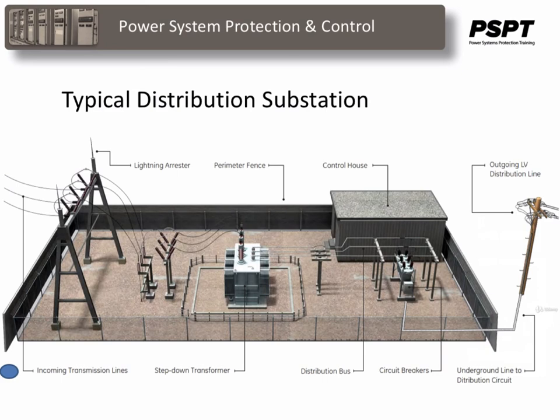There is usually a control house associated with a distribution station that houses the relays, the metering, and the communication gear that's required to run the station. The station can be double this size if it has two transformers and two sets of lines coming in, and very seldom do you only get one set of feeders coming out of a distribution station. You usually have a low voltage bus that facilitates anywhere from 4 to 10 feeders coming out of the station, and certainly the protection schemes would have to be multiplied by the number of equipment in the system.